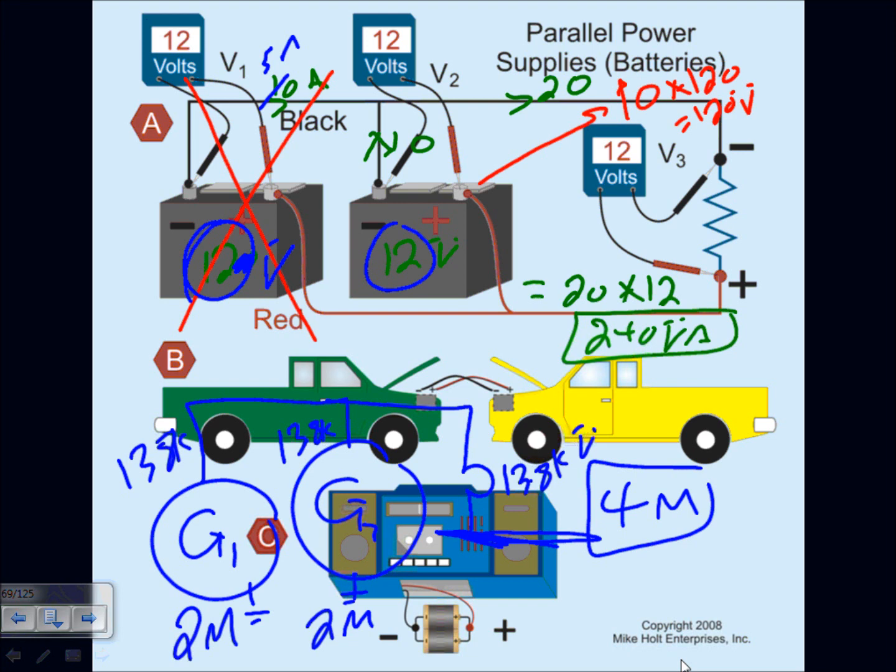On my Jeep, I just had a bad connection. My battery was fully charged, but it's like corrosion. If you wiggle it, you'll get the spark and it'll be a full battery. That's high impedance. You have a high impedance right here, so you're choking the voltage. If it's 12 volt, you lost, say, 4 volt in that impedance. So your coil is getting 8 volt, and you're trying to push current at 8 volt, and you can't start your engine.